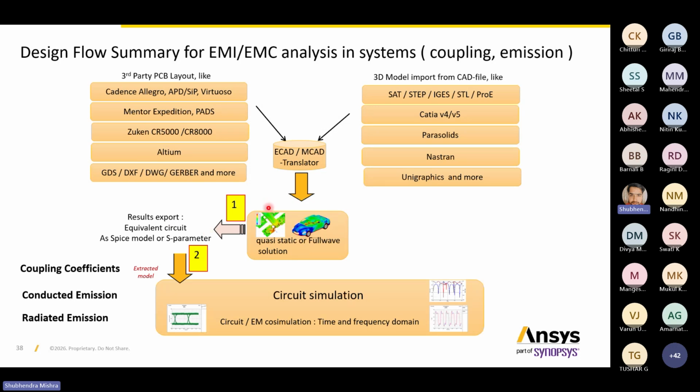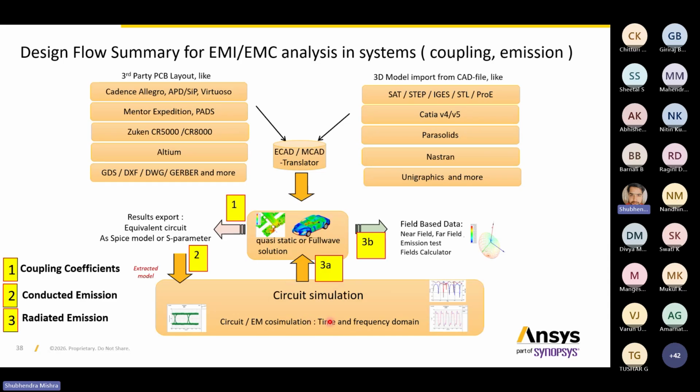So this is basically a multi-physics part where one tool is getting connected with another one. For example, when we are doing the 3D ECAD analysis, the SIwave tool will be required, and after extracting the S parameter data, I will move to the circuit simulation, and after completing your circuit simulation, we will analyze your near field and again move to the SIwave with proper data. You don't need to worry about data loss when we are going from one tool to another.